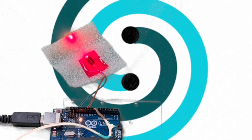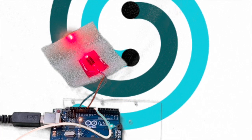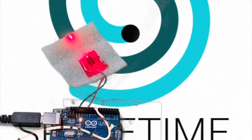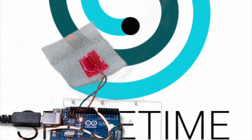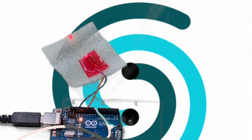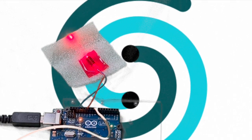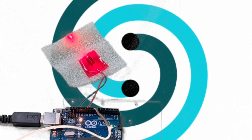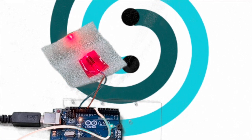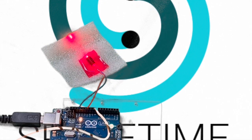And this is how you can use the digital input signal with an external interface such as switches to regulate the control using the Arduino board. Once we flash this code, we don't need this computer anymore. We can simply disconnect this and connect it to a standard USB power supply, and then this would work as we see it now. This is the advantage. You can program your Arduino board and then plug it into any device, and that is why it becomes extremely popular. So these are some of the basics of pulse width modulation.